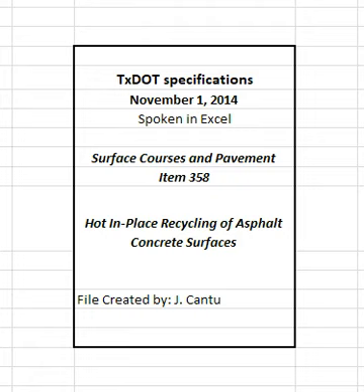A placement lot is defined as the area placed during a production lot, 1 day's production. Placement lot numbers will correspond with production lot numbers. 6.2 Placement sampling. Provide the equipment and means to obtain and trim roadway cores on-site. On-site is defined as in close proximity to where the cores are taken. Obtain the cores within 1 working day of the time the placement lot is completed unless otherwise approved.